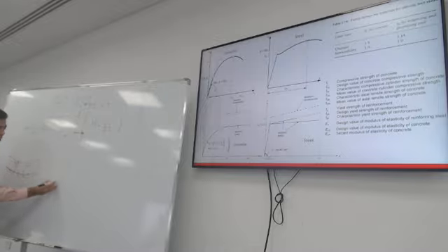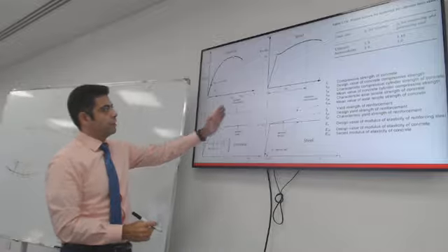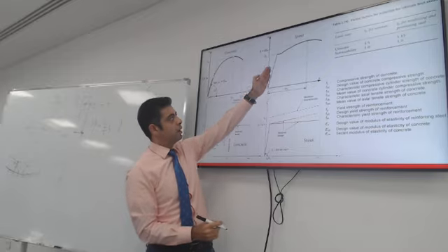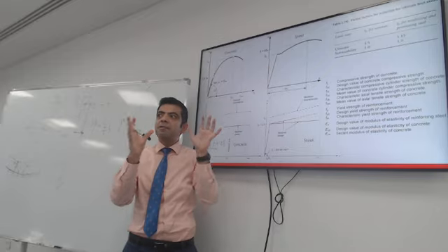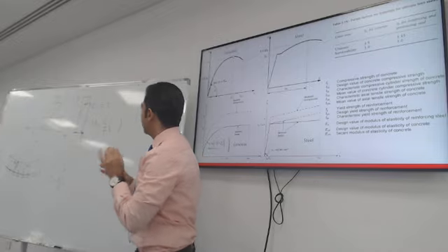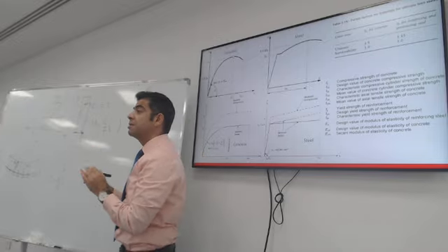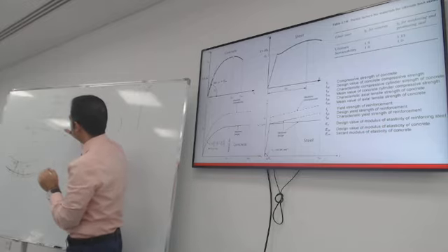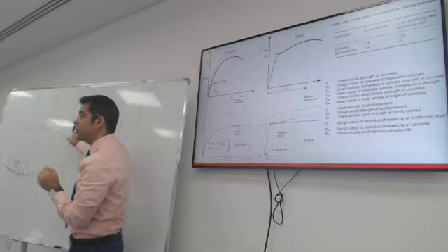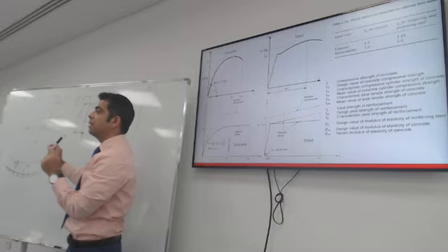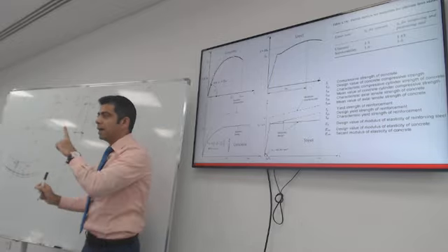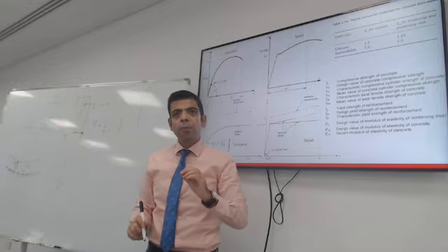So how do you calculate the strain? It's pretty much the stress divided by the modulus of elasticity. So the modulus of elasticity applies in the straight part, but past that part the behavior is different. The assumption that we will make is that the strain in concrete and steel is going to remain equal. If I can get your attention for a second, this is a very important concept.